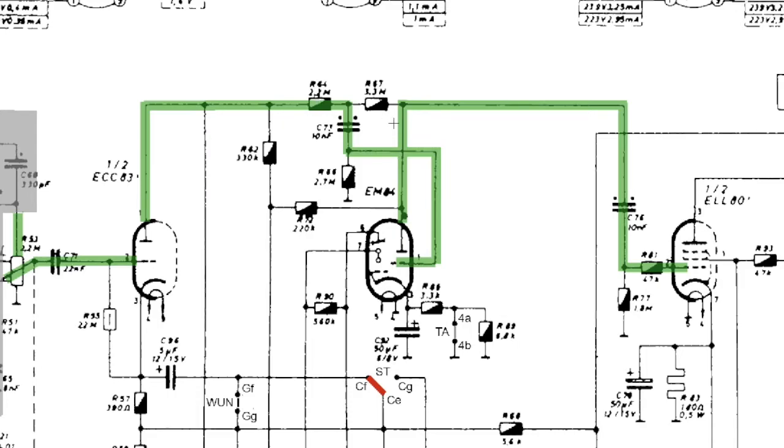Now, this is comparable to an inverting op-amp circuit, where you have the feedback resistor, RF, and the input resistor, RI, and the ratio of the two would give you the gain. Well, that only works if the amplification stage has infinite gain, and you control the actual gain by the combination of resistors. Because this does not have infinite gain, that one is slightly higher to compensate for that and to give you that -1 multiplication factor.